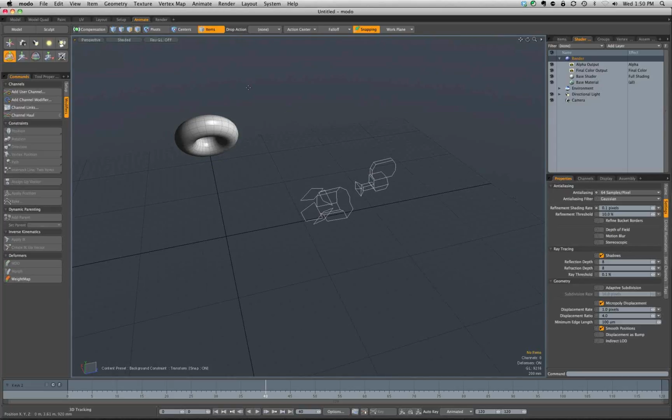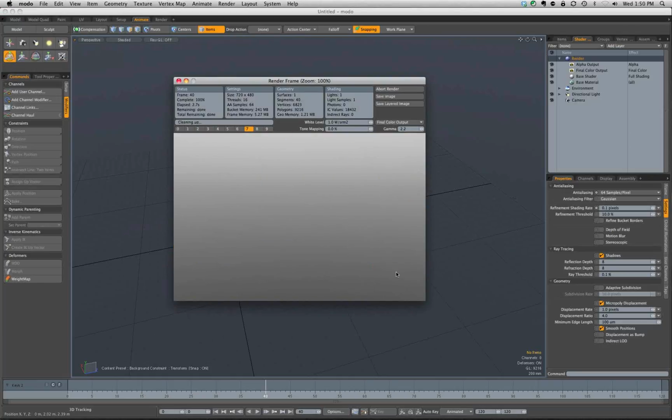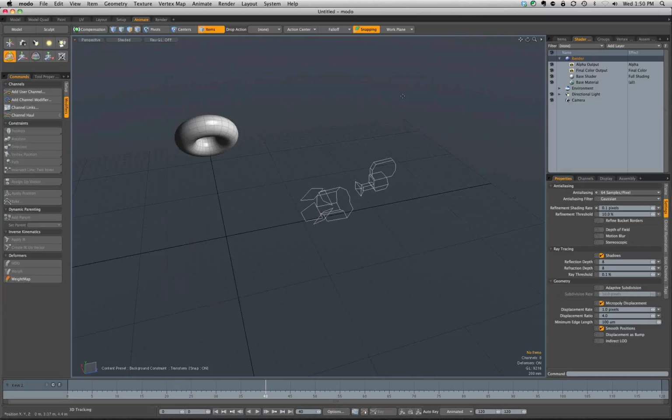When the other Moto license comes on, make sure it's on the internet, make sure it's on your network. It will see that this license is running and say, okay, something else is running. Do you want to render in slave mode? And you say yes. And then up in your preferences, you just give it a directory, and it will start shooting renders over. When you render right now, we got these yellow buckets like that. When you have the slave mode on, it will actually be showing you, I think it's blue or green, showing you the other processors on the other networks are rendering. And it works pretty well.